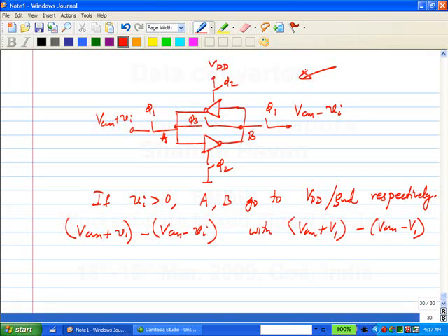So clearly what that indicates is that this making a decision, regeneration, finally the output is non-linearly dependent on Vn. It's only telling you whether the input is greater than 0 or less than 0. But we want to subtract Vn minus V1. So any subtraction has to be done before you try and make a decision. Is that clear? You can't use comparator 1 for input, comparator 2 for reference and then subtract the two outputs. That doesn't work. That's clear? So whatever you have to do, the subtraction has to happen before the comparison happens. Does that make sense? Okay.